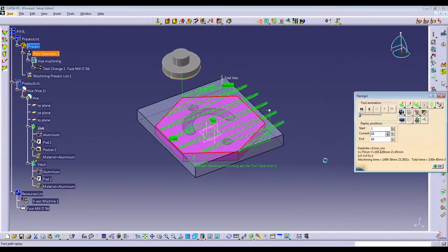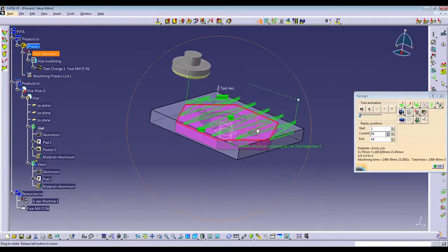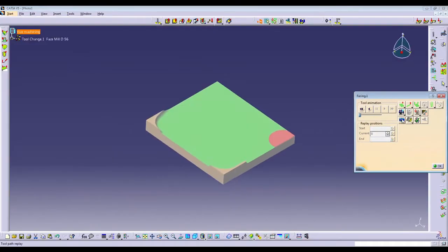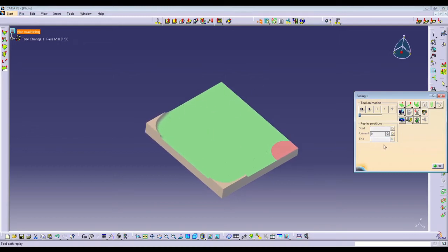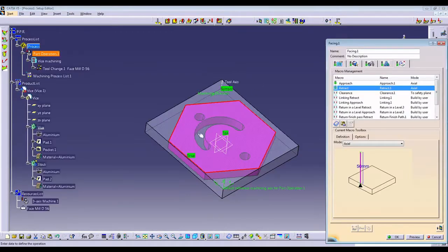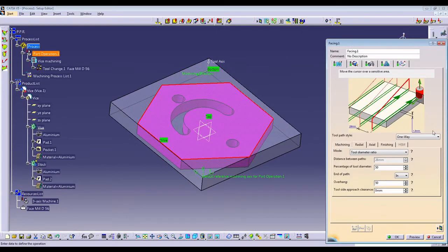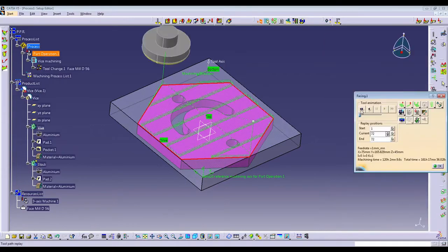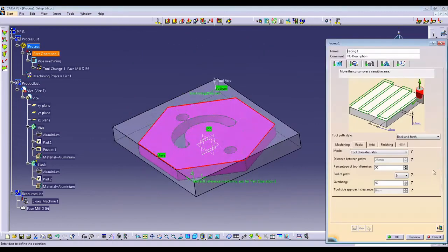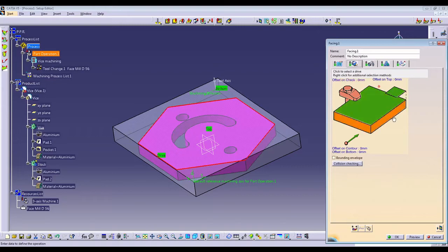Okay, then let us look at the video. See, now the cutting is not correct, so maybe we have to change this one way back into back and forth. Let us look at this. Oh, it does not create the correct one, because I didn't change this contour, so I need to go back to this plane selection.